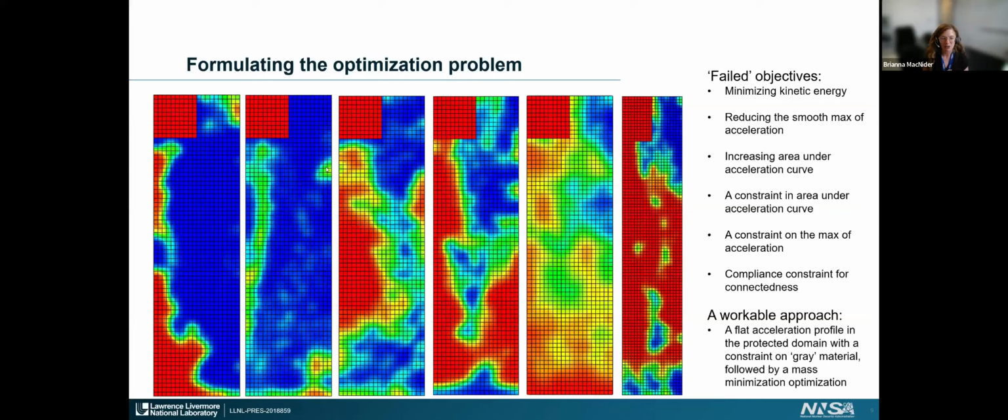These approaches here do have a volume fraction constraint on them, but the problem is that the optimizer is very, very happy to go down to the volume fraction that you specify, and then just go further down than that and find a good design, good from its perspective, at a lower volume fraction than the one that you specified. It's a non-unique design space, and also if it throws a bunch of soft material in there, it's similar to basically putting foam or some sort of crash or landing pad in the design. And so from the perspective of the actual objective function, this works very well.